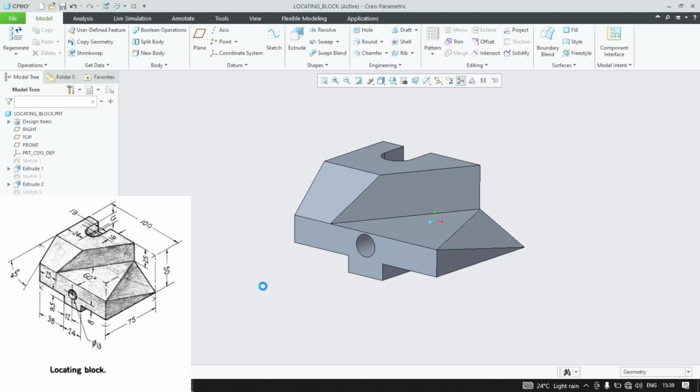What might be the issue is the rectangle size is not exactly 50 into 100, it is 50.95, right? As you could see on the locating block picture, it is 50 from the corner of this edge, but not exactly at the bottom.